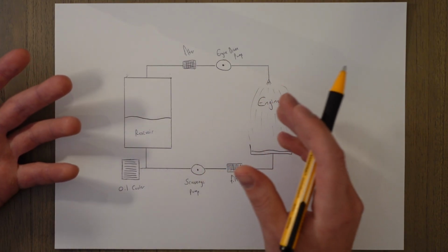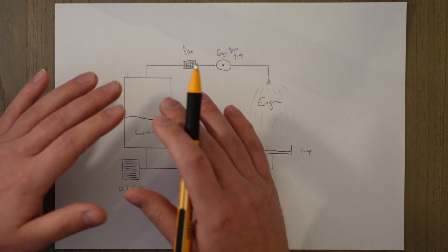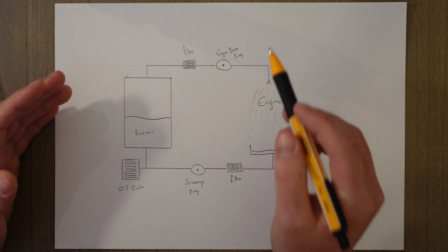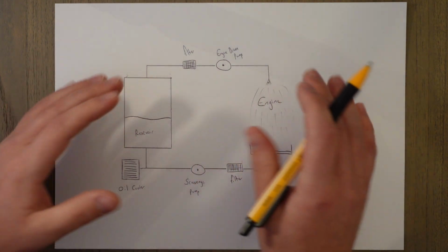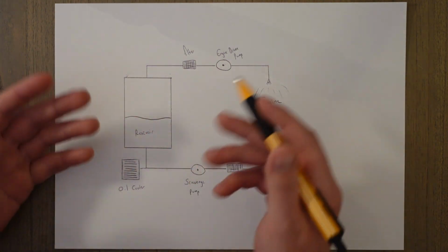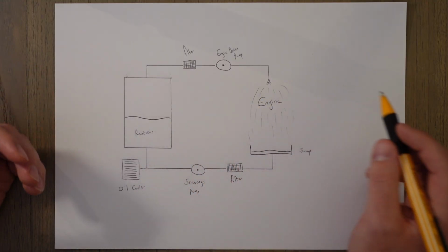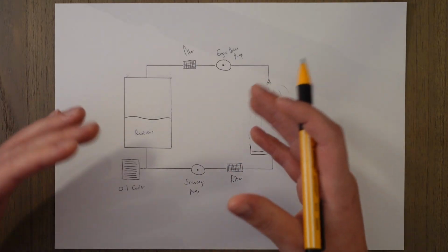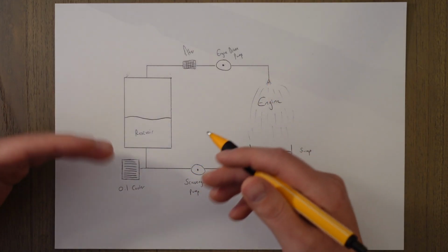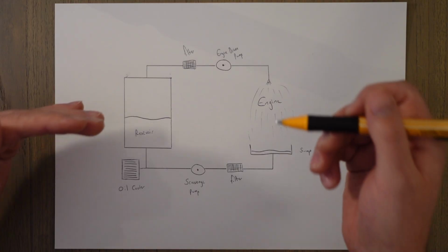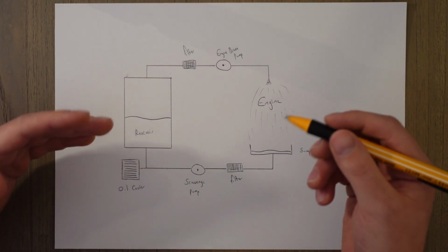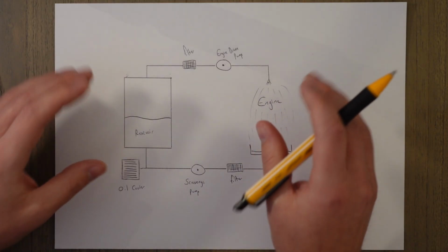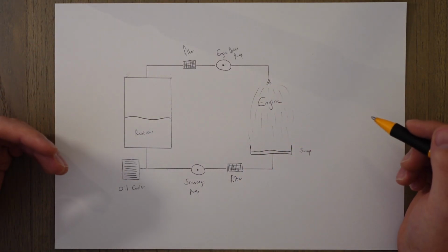It's basically a very simple ridged structure, I think would be a way to describe it. The oil fills up these ridges and air passes over the ridges and the air cools the oil that is contained in those ridges before it heads back to the reservoir. And these ridges, these fins you might call them, are used throughout the engine where the temperatures get high. You might see them on the outside of the cylinders, for instance, and that just allows lots of air to get in and take away heat from those components.